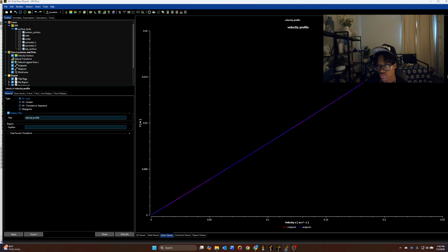This is Couette flow. It's supposed to be pretty linear. And the reason why it's super linear right now, and we haven't touched anything luckily, is that the Reynolds number is very low. Now it is a little bit bent, but again, we're not using air or water. I'm using a pretty viscous fluid right now. So I know that's also playing a factor in here, but our Reynolds number is still relatively low. I think with everything that I have, I'm coming in at about a 90 for the Reynolds number. So that's pretty good. But if you change the values and use maybe air or water, you could definitely come in with like a 10 or 20 and this would look super, super straight. But this is pretty much everything.